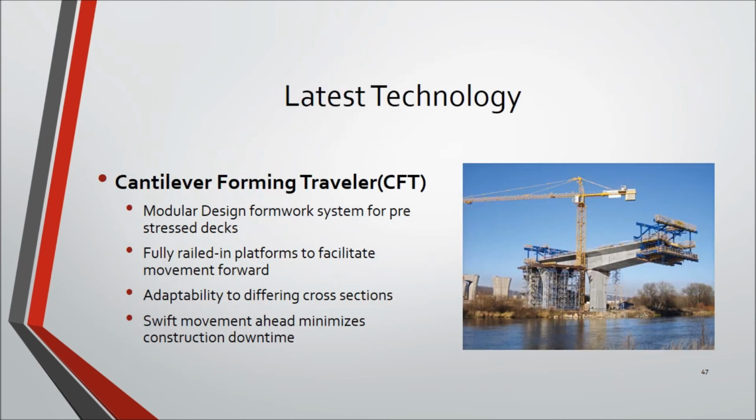Now, as promised, we shall check out some of the latest technology in the formwork systems industry. First one is using cantilever forming traveler. This is a rail-mounted modular formwork system, which swiftly moves ahead on cantilever bridge sections. It is also adaptable to varying deck cross-sections.